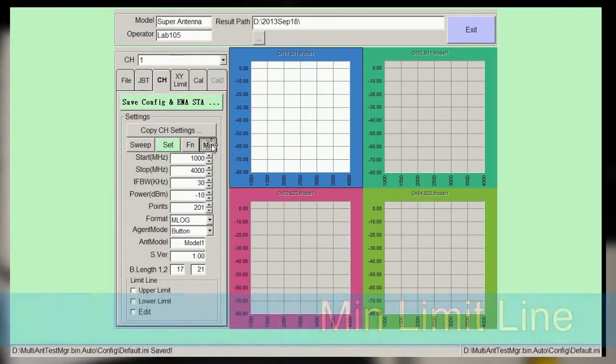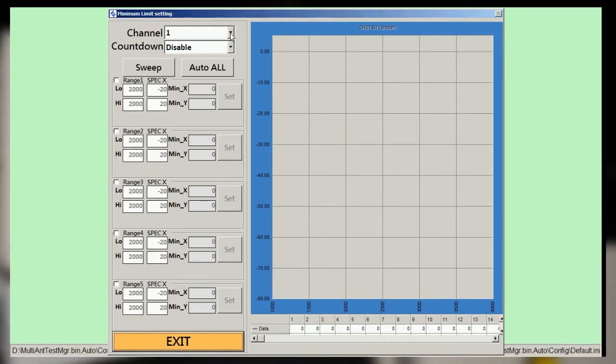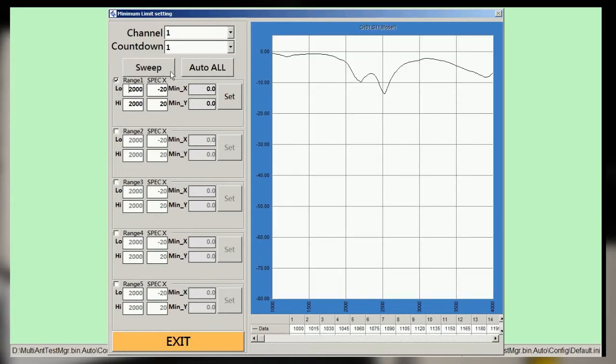Limit line minimum is for characterizing in-band frequency versus magnitude. First, have a gold sample swept, then move the cursor along the trace waveform; the corresponding frequency appears, giving an idea of the minimum magnitude data and frequency. Then set the in-band range and the preferred magnitude. Then with a DUT in position, click Set, and it reports the DUT's in-band characteristic, the minimum magnitude versus the frequency.